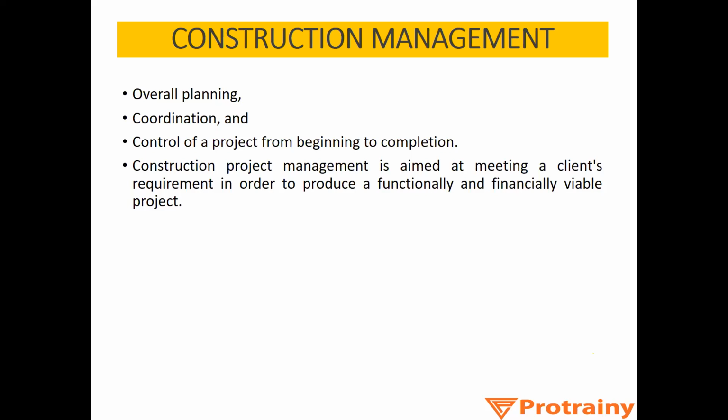You even have to coordinate with the architects and structural consultants. From my practical experience of site, many times for the same structure, the drawing of the architect will be different and the drawing of the structural engineer will be different. And the drawing for the MEP consultant, that is mechanical, electrical, plumbing, will be completely different. Now you need to coordinate between all three parties and make sure that whatever ambiguity you have in the drawings is resolved, and not only resolved, it should be resolved before time. At various times it happens at site that people start working on a project and after that the work is completely stopped. Why? Because there was an ambiguity in the drawing.